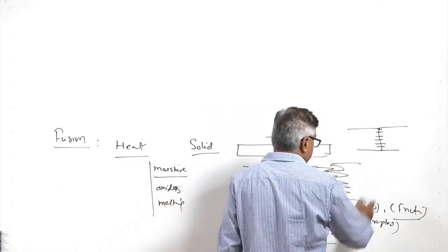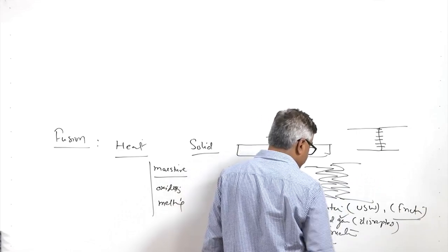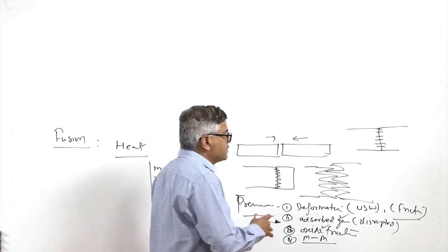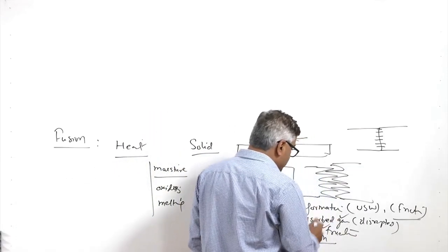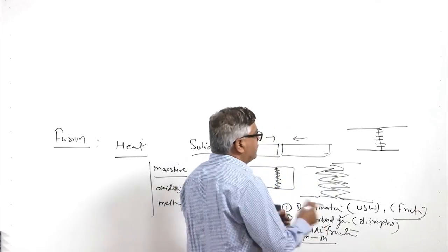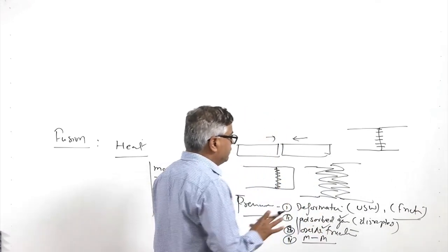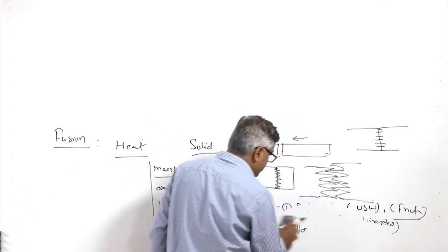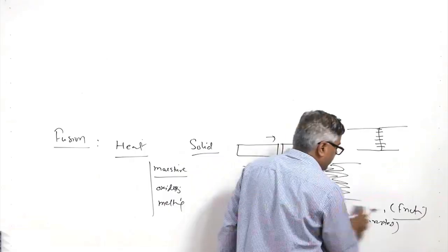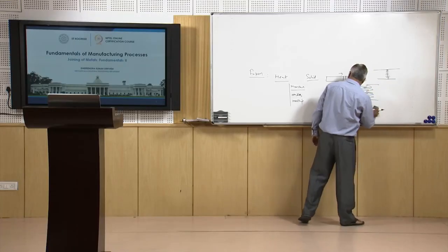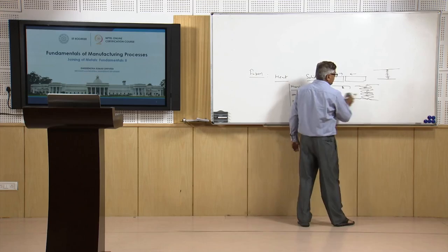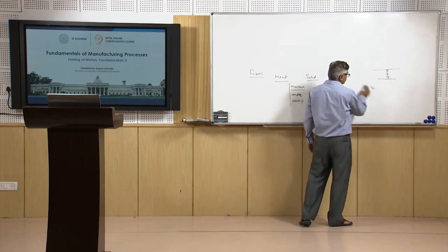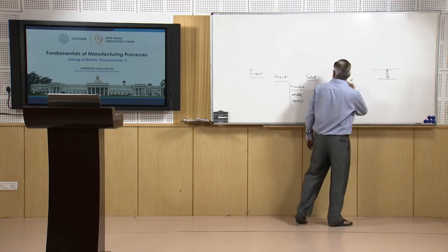So, the disruption of adsorbed gases and the fracture of the oxide layers present at the surface is mandatory for having the direct metal to metal contact between the components being joined in the solid state. So these were the different kinds of things which are realized with the application of the pressure in the solid state joining processes like friction welding, ultrasonic welding, explosion welding, and